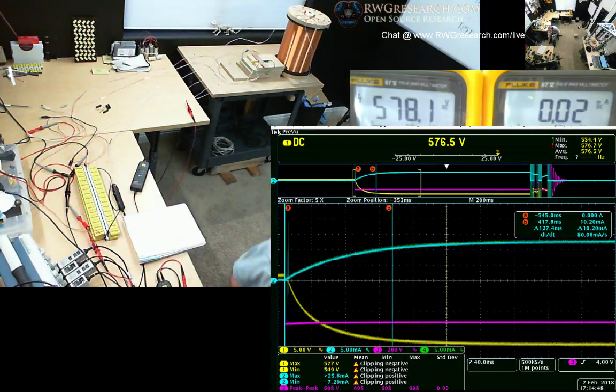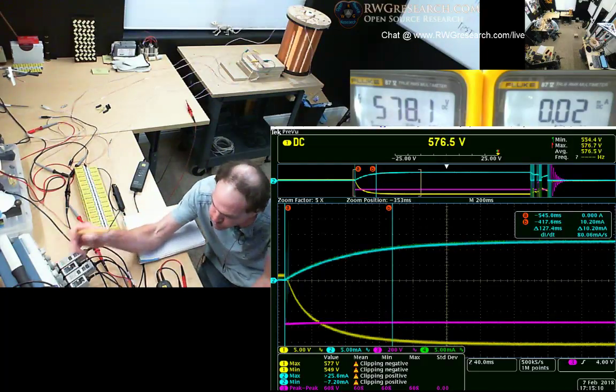Okay. And then it says, calculate the time for the required armature motor RPM chosen. Calculate the time for the current to rise about 20% of the maximum value as determined in step 1. Okay, so 20% of 12. So move your B cursor over to 2.4 milliamps.